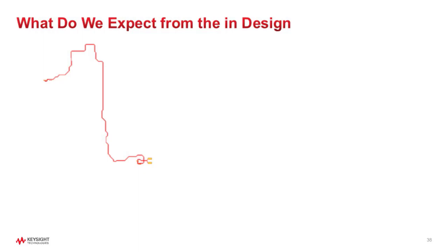We'll send that out later, but just to conclude here, I was showing you how to import a board and look at the trace we want to simulate, which is the USB trace shown here on the design. On the left, we want to see, is it consistent with what we expect? You have the TX is 5 gigabit per second, Nyquist 2.5, and then the length is 7-inch.